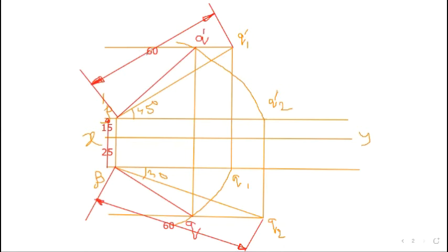This is difficult, so for this reason, we just overwrite on this line. So all of you, when you give the dimension, erase the middle part of the dimension line and then write 60. Similarly here 15, erase the middle part of the line and write 15. Similarly here also erase the middle part of the dimension line and write 25. Clear? So this is about problem number 3.